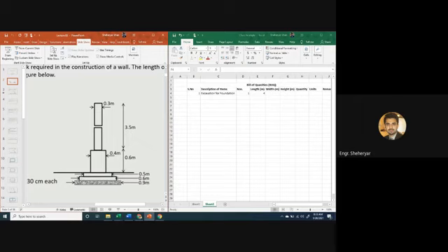Can you incorporate this PCC, which is having a width of 0.9 meter, in this excavation? Definitely no. So you will excavate the ground with a width of at least 0.9 meters, so that this largest size of the footing can be accommodated. Is it clear? Yes, sure. So the width of excavation will be 0.9 meters.